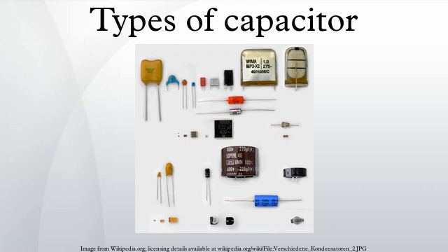Temperature dependence. Capacitance typically varies with temperature. The different dielectrics express great differences in temperature sensitivity. The temperature coefficient is expressed in parts per million per degree Celsius for Class 1 ceramic capacitors or in % over the total temperature range for all others.